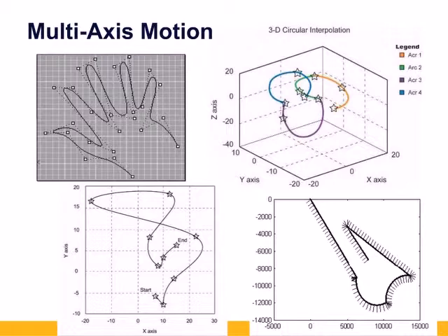Another common application would be an XY system, with the third axis as a theta axis. Here shows the advantages of the ACR's look-ahead feature that keeps the theta axis at a perfect 90-degree angle from the path. Even if the path reaches a point, it'll rotate the theta axis before advancing the X and Y. Pretty cool motion. You may ask, how does the ACR do it?